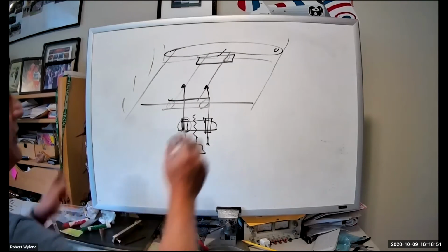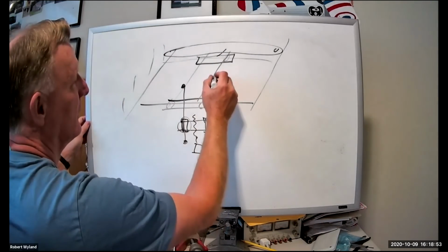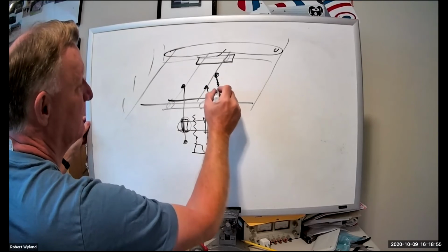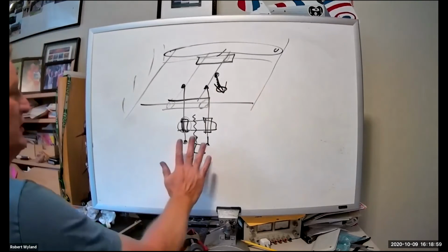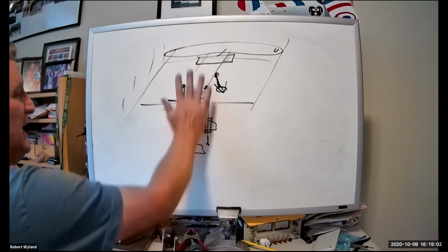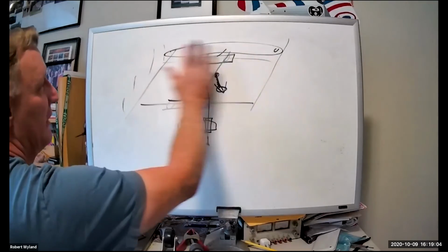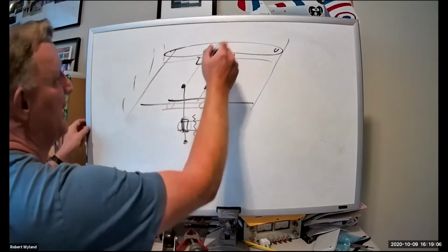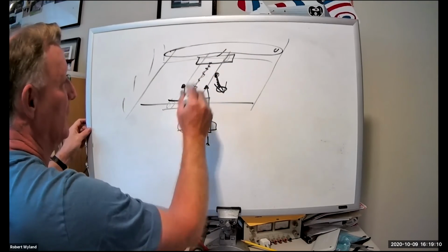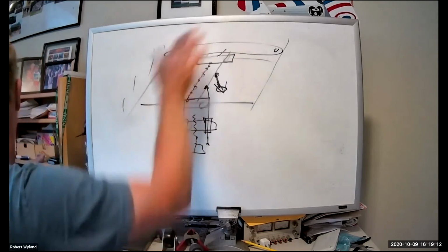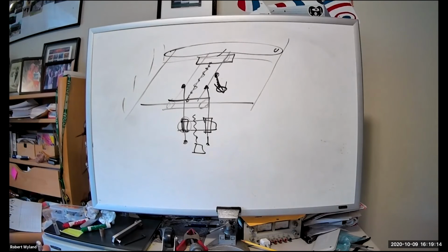So in a 3-dimensional printer, they'll have one little gun right here that's ejecting plastic out of it, squirting it out. By sliding these bearings up and down with a motor, and then sliding these bearings back and forth, and then you'll also do the same this way. You'll have another drive, this motor and a lead screw. You can slide the carriage back and forth. So you end up with bearings that slide along in all directions eventually.